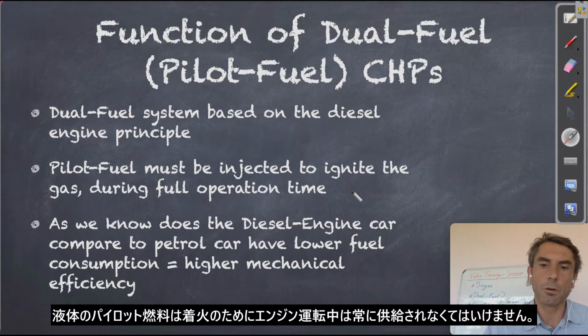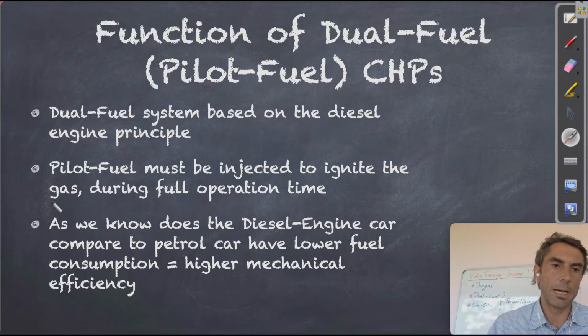So it means from the startup we need pilot fuel, we need it through the whole operation of gas mode, and for the cool down phase until the engine stopped. So the pilot fuel will be needed all the time to ignite the gas.